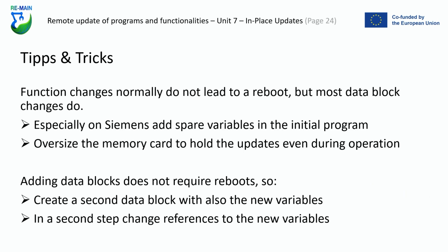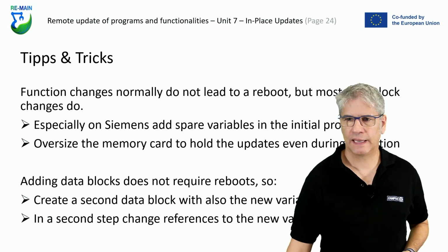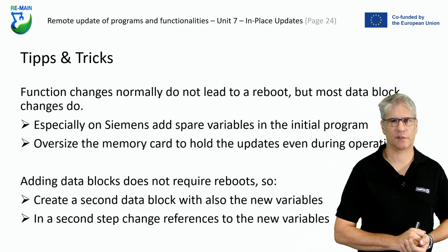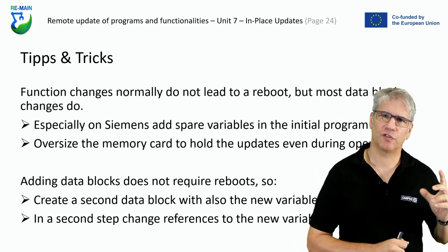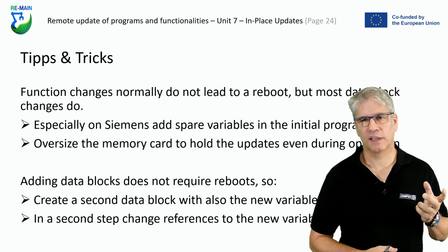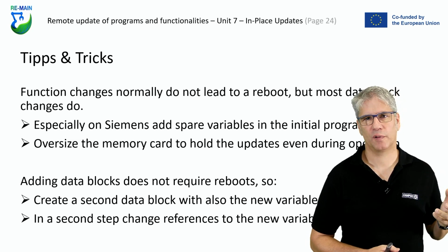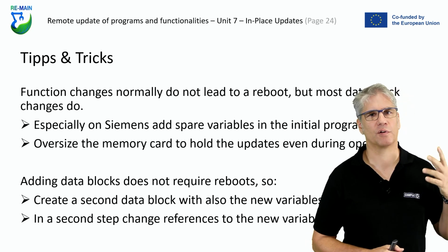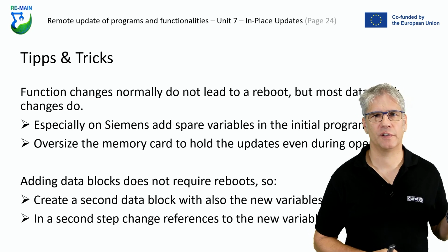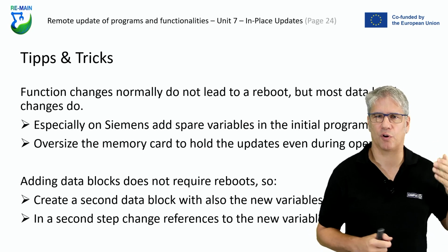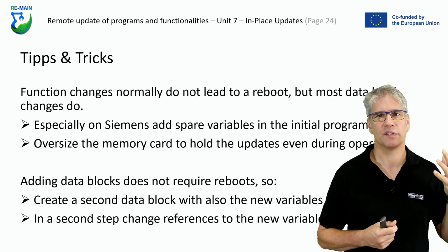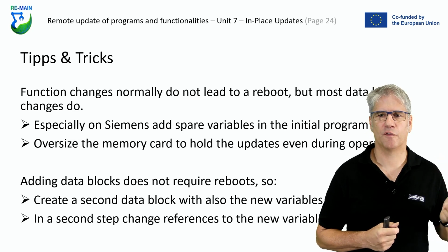Finally, there's some tips and tricks that could help you preventing reboots. So if you change data blocks, normally a reboot is necessary. But you can circumvent this. There's a trick to add more variables in advance. So if you know that you're going to extend your system in the future, you could introduce variables that are not used in the current program, but that are reserved as some kind of spare for the future.